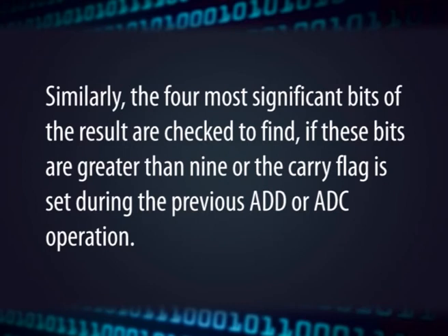Similarly, the 4 most significant bits of the result are checked to find if they are greater than 9 or the carry flag was set during the previous add or ADC operation, and 6 is added to the most significant bits.